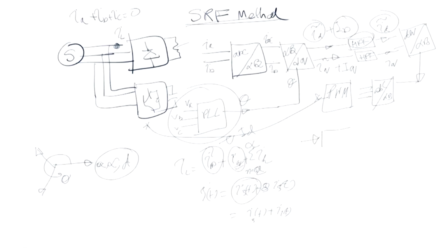So, those are a few challenges, and the PLL is being challenged to get that real actual value in that case. Anyway, these are the complex problems with the SRF system. Now, we shall take one example with this ANN, where the concept of this SRF will be combined. Ultimately, how accurate you generate this matters, and the high frequency component is split with a high pass filter and low pass filter, and it is subtracted here. So, this is the constitution of the high pass filter.